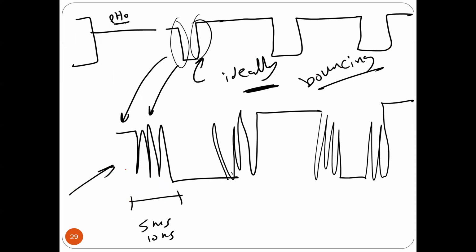you are going to have here, guys, one interrupt. You're going to go execute the interrupt. You're going to come back from the interrupt. This one is going to count another interrupt here, another interrupt here, and so on. That's why when you press one time, it's going to trigger 3-4 interrupts. Every time there is a falling edge this way, it's going to be taken as one interrupt. You got what I'm saying? Okay, how can we solve it?